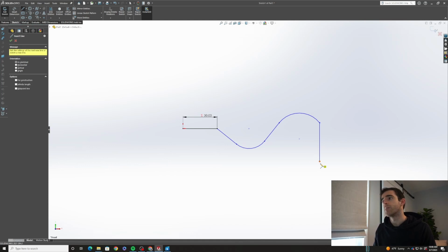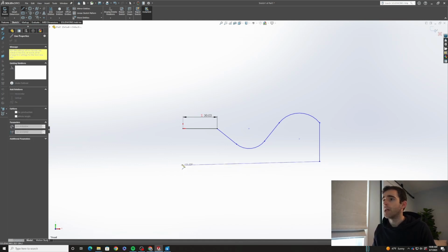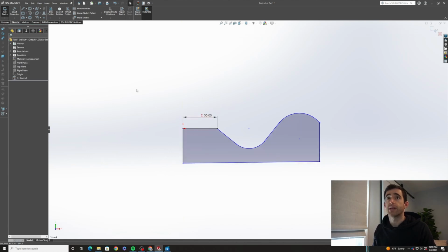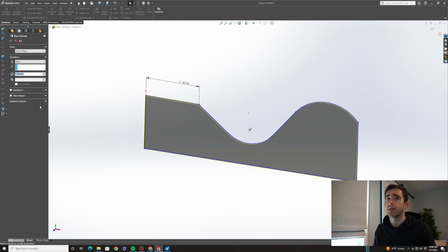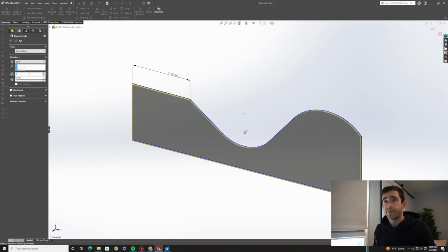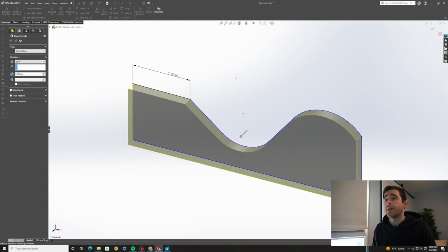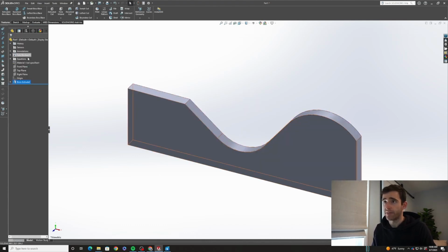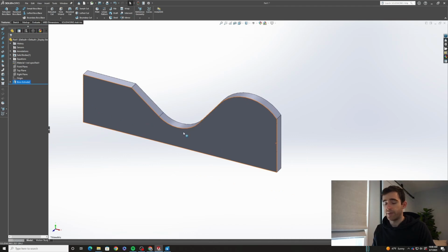The last keyboard shortcut I've used a little bit is less robust in my opinion, just because you have to kind of get it just right. But say I'm creating a feature. I've set this to 5. And my mouse is out here, whatever, I've selected this contour. I can press D and it brings the check mark right to your mouse, and you click OK. And it's just less back and forth with the mouse. That's useful sometimes if your mouse is out in this area, the design area, and you want to quickly move on to the next feature instead of going back to the green check mark.